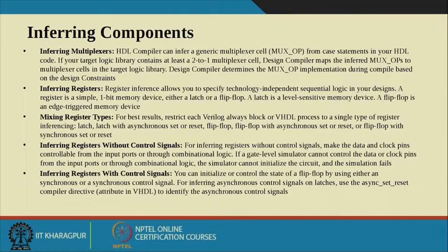Just by writing MUX_OP in the HDL code, I can infer a general multiplexer. And if your target logic library contains at least a 2:1 multiplexer cell, Design Compiler maps the inferred MUX_OPs to the multiplexer cell in the target logic library.